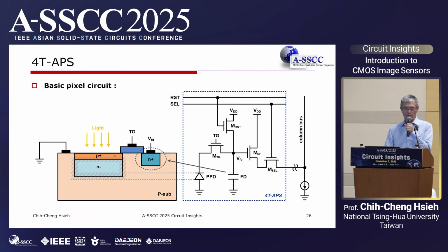It implements one more layer on the surface to protect the surface interface state, to protect from coupling, and more importantly, it creates some behavior called pinning. Pinning means that when we do reset, all the depletion region will be increased and touched together on the N-region to clear all the charge inside this node, to do the charge transfer to here.